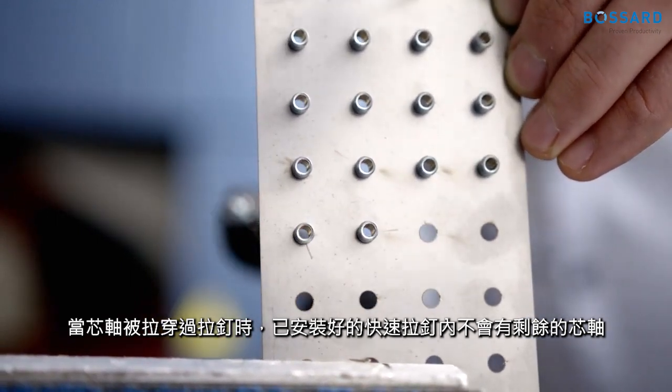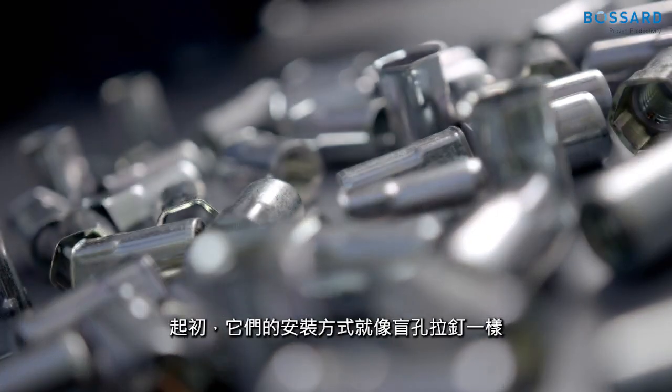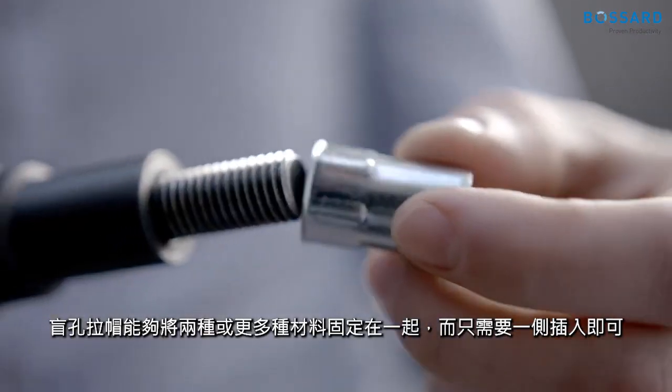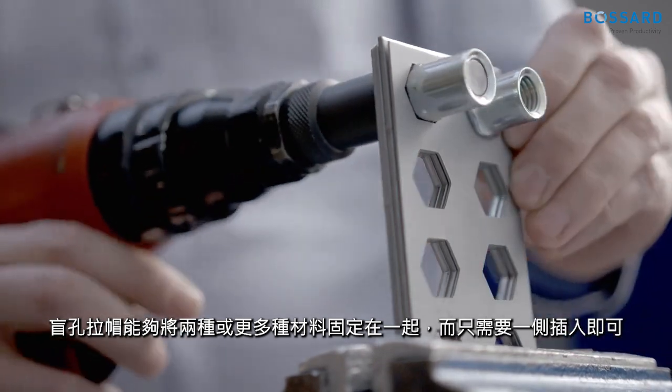As the mandrel gets pulled through the rivet, there is no remaining mandrel within the installed speed rivet. Now we are going to leave the world of blind rivets and jump directly into the world of blind rivet nuts. Blind rivet nuts are multifunctional fasteners. At first, they work like a blind rivet because blind rivet nuts are able to fasten 2 or more materials together with only one-sided access.